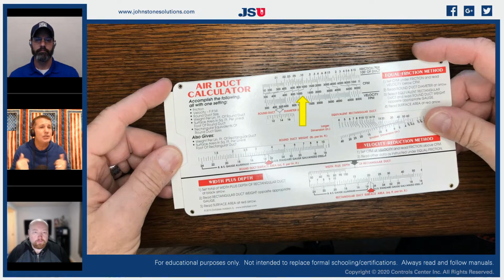So I try to design my ductwork around 0.1 inches. Typically on my supply, I'll do 0.1, and on my return, I'll do 0.08. But 0.1 is typically where I design my ductwork.